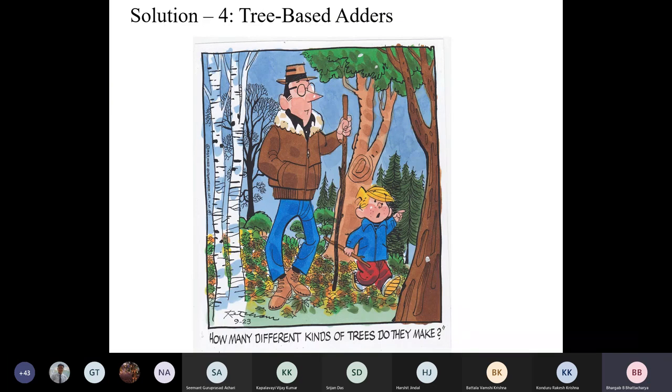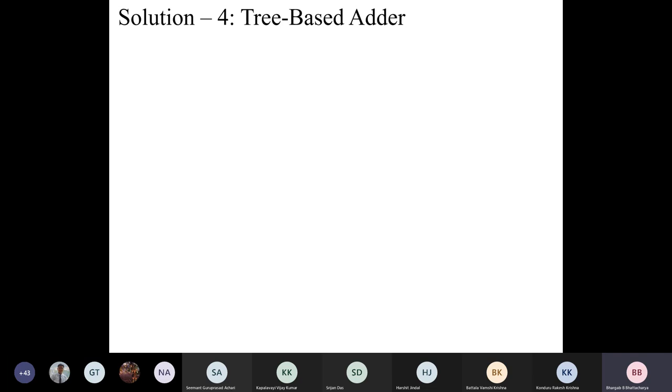And so I'm going to present before you solution 4, which is a tree-based adder, the carry look ahead tree, CLT. That's also some kind of tree-based adder, but there are other important and nice architectures which are also based on trees that we will discuss now. Okay. Let us first recall our 4-bit CLA, because that describes very well the cost of the architecture as well as the delay propagation.